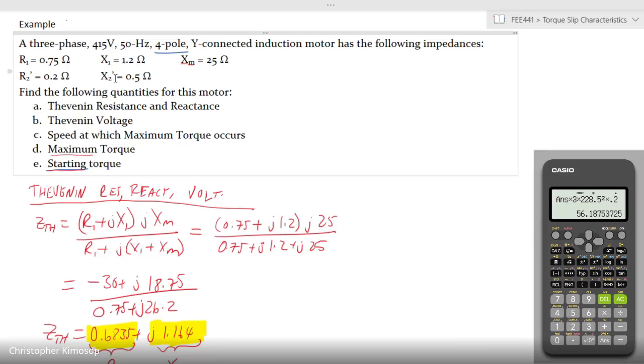When we were generating the equivalent circuit, there's a point where we eliminated the equivalent transformer between the rotor and the stator. So the prime doesn't really affect it. Those are the actual figures. Sometimes when I'm writing, I leave out the prime, but it does not affect the actual calculations.